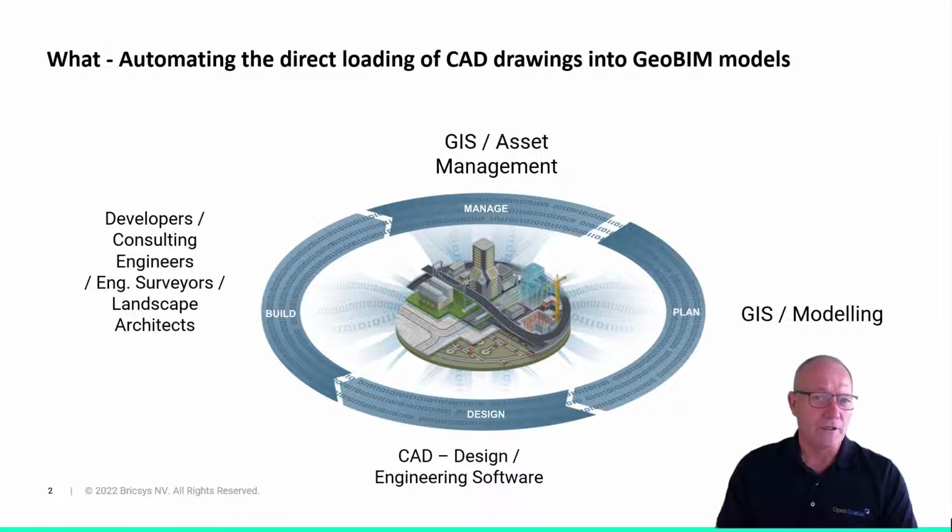What I'd like to do is just take a look at the workflow, and what we're focused on is the transition of data between design and as-built documentation and how we get that information into GIS systems. So it's this little part of the workflow right there. What we're doing is front loading so that the CAD person can add the attributes within the CAD drawings in such a way that they can get consumed and validated within GIS. And that produces huge efficiencies, and I'll show you that.